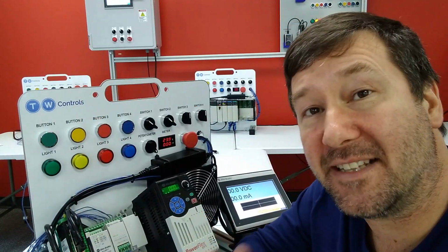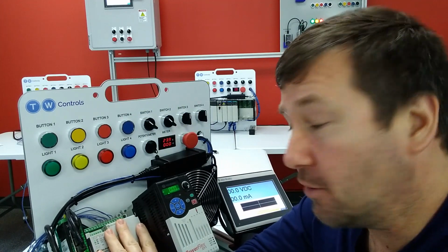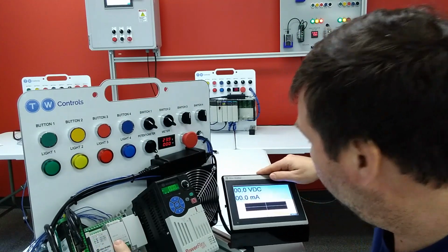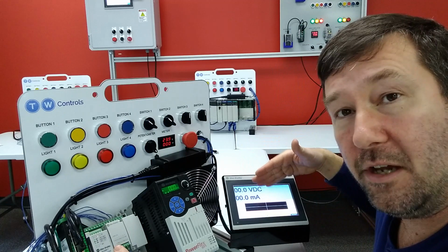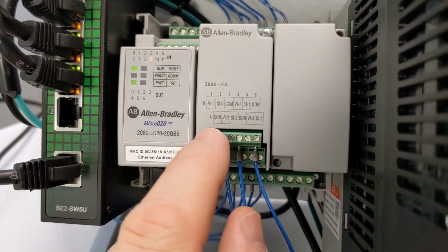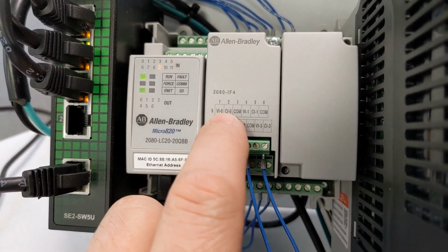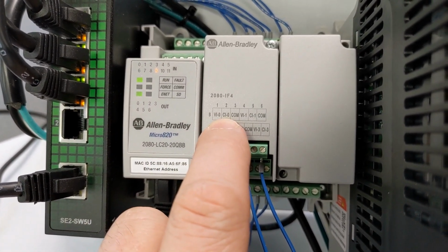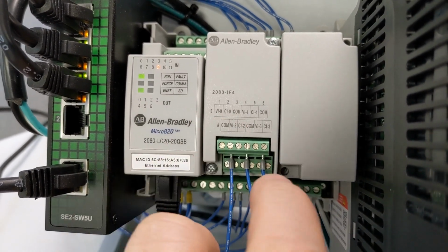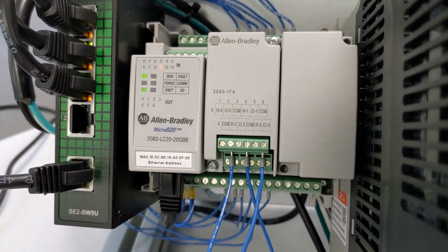Now let's simulate that same signal to an Allen Bradley Micro 800 PLC. And I've also made it where we can see the value really clearly over here on the panel view. To simulate a current source, we're going to need to connect a wire to the current input, and we're going to use input 0 for this, so CI-0. And then we're going to need a connection to the COM terminals. We're going to use these two wires.